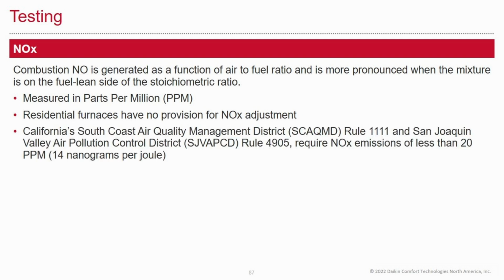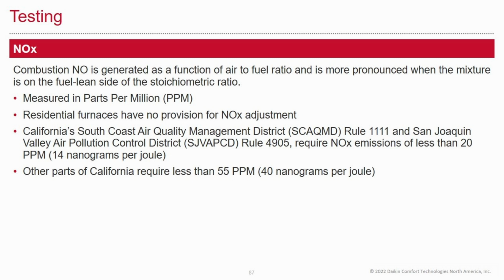California's South Coast Air Quality Management District, Rule 1111, and San Joaquin Valley Air Pollution Control District, Rule number 4905, require NOx emissions of less than 20 parts per million. Other parts of California require less than 55 parts per million.